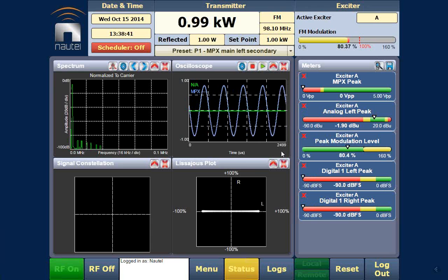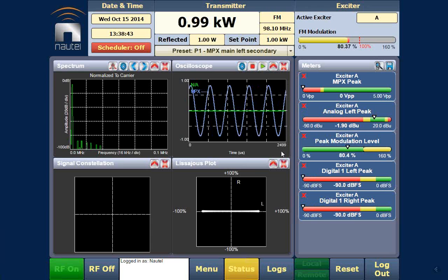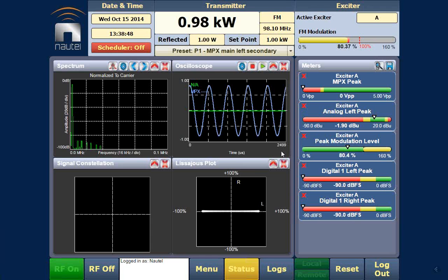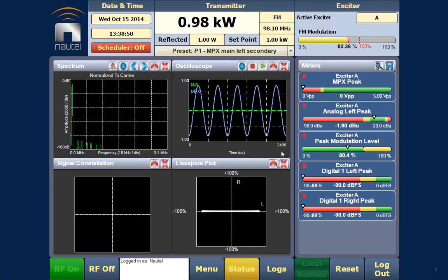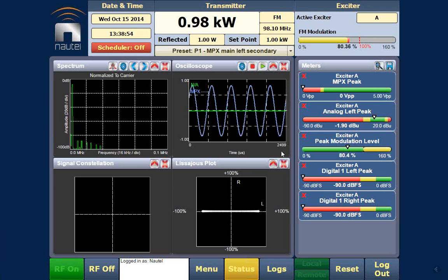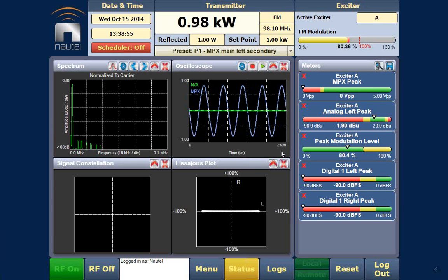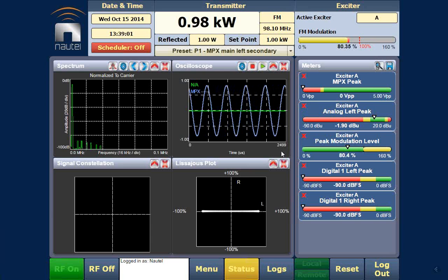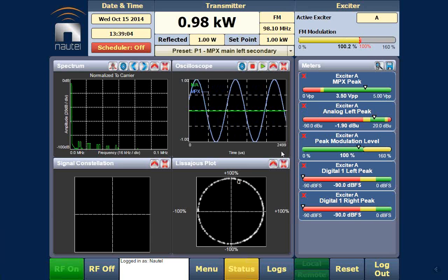Left is still connected because I actually set this up where Leah would set up the left once we did the switch. This way it wouldn't recover to the MPX automatically in preset 2. It switched back to preset 1, said MPX is still not there. Now it's running at 2 kilohertz on the left channel again. Perfect. And now we're going to reconnect the MPX and get ourselves right back to square one. It will shift back to the desired MPX input. Perfect. Okay. Excellent. Well done.